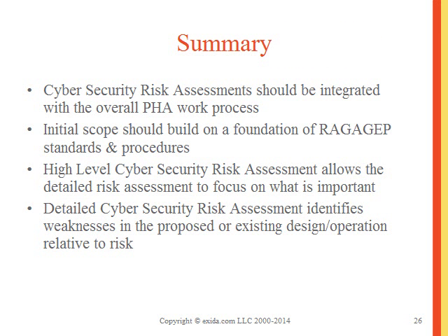So in summary then, you can see that the risk analysis is just a component of the overall process hazard analysis, that is the cybersecurity risk analysis. The initial scope needs to be built on a foundation of recognized and generally accepted good engineering practices, RAGAGEP, standards and procedures. The high-level security risk assessment allows detailed risk assessment to focus on what's important.